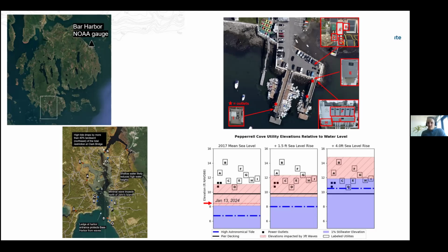So what we can do then is assess flood risk using water levels from things like FEMA maps or the nearest tide gauge, and add sea level rise to them. But it's much better when we can grab a photo from, again, this is in the beginning why I showed that the types of events we've seen already are pretty representative of a good design flood event.